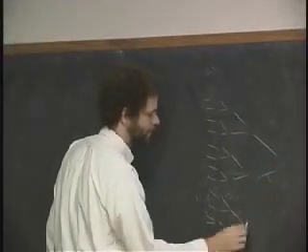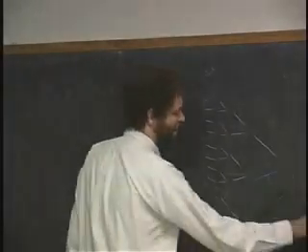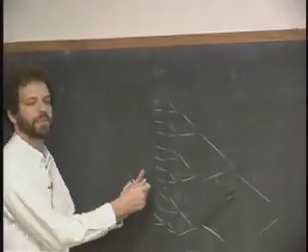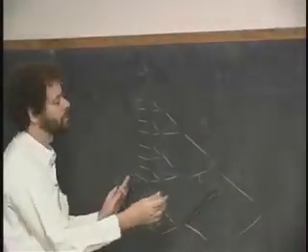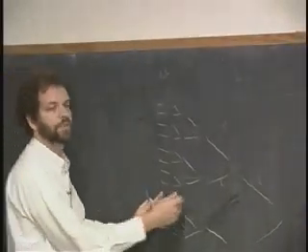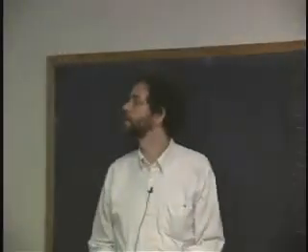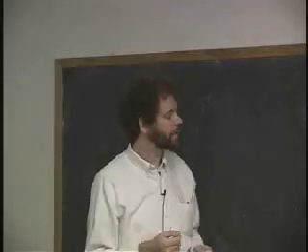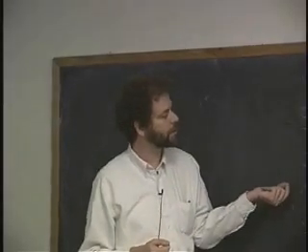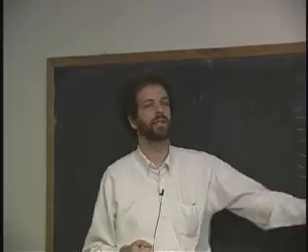We've run out of room here, but we'll just pretend that there's more. If you have n elements here, the depth of this tree is going to be log n. As the number of elements I need to choose from grows, the depth of this tree grows too, with order log n depth. That tells you that the latency of trying to get to a particular bit is bound by log n as n gets large.